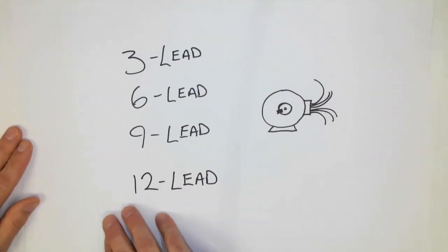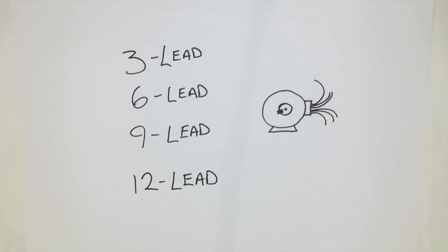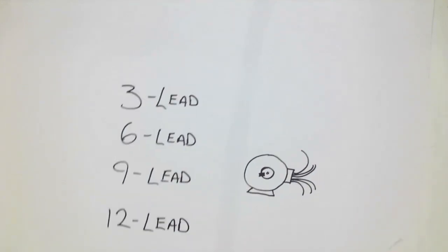Now, the types of different stator connections that we have in the electrical industry are labeled as per the number of leads that come out of the motor junction box. We have 3 lead motors, 6 lead motors, 9 lead, and 12 lead. These being the most common forms of three-phase machines in North America. What we're going to start with is 3 lead machines.